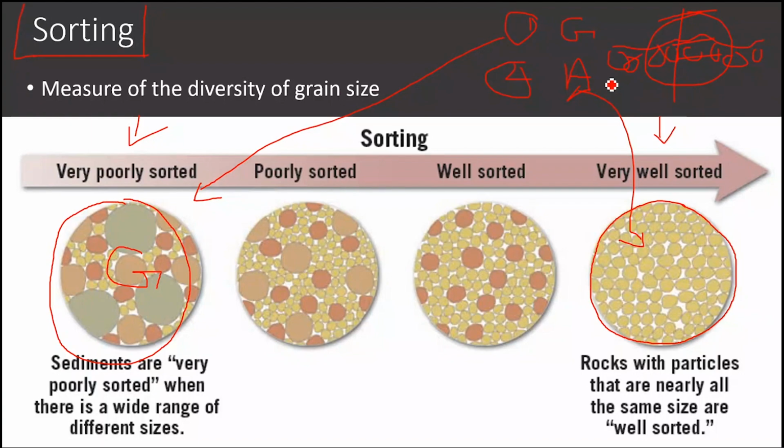For example, if you are talking about a wind-blown deposit, it will have a uniform nature over a large areal distance, because when wind affects a region, it affects a larger region. But if you are talking about a glacier region, the glacier deposits may not extend over a very large region, and when you move from one place to another, the characteristics of the sediment vary. That is facies identification, identifying in what kind of environment these rocks have been formed. That identification and understanding will help the civil engineer take a proper decision on the subsurface or foundation characteristics, or the materials you are going to use for the construction.